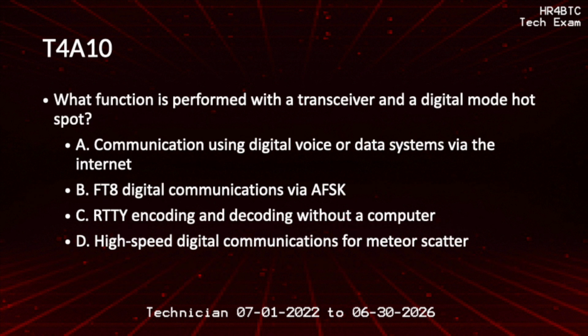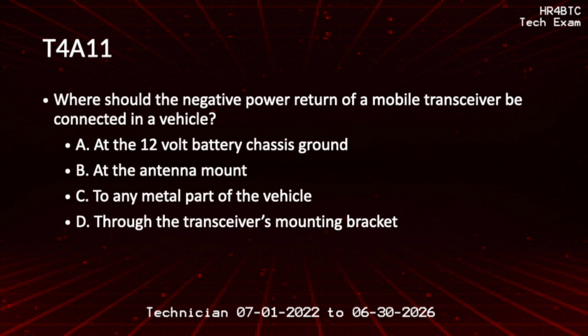What function is performed with a transceiver and a digital mode hotspot? Communication using digital voice or data systems via the internet. Where should the negative power return of a mobile transceiver be connected in a vehicle? At the 12-volt battery chassis ground.